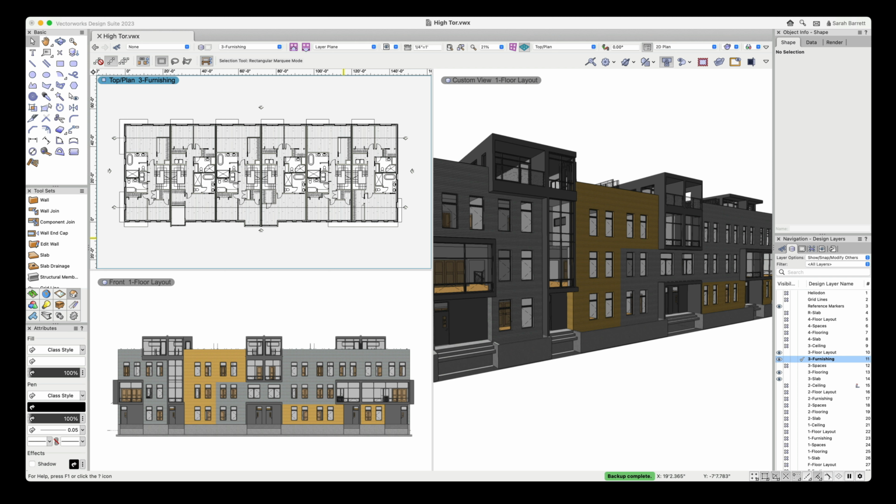When sharing the model itself, and not simply drawings extracted from the model, there needs to be a certain level of accuracy, consistency, and organization. The specific level of accuracy can be outlined in your BIM execution plan, but I think it makes sense to create a model to the level of detail that will be seen in your plan and elevation drawings. Anything of higher detail can potentially be created by overlaying 2D detail on a model viewport or drafting completely in 2D.